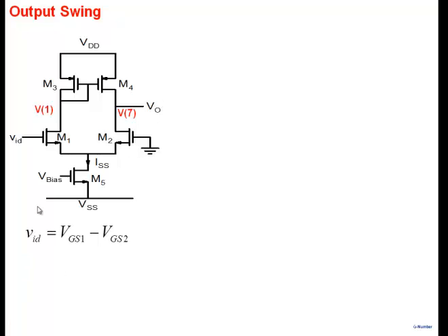All right, so here I've put a ground here and applied a differential voltage here. And the differential voltage that you see, if I do a KVL, this is nothing but VGS1 minus VGS2, right? VID. If you go from here, come here, and then go here, you get VID is VGS1 minus VGS2.